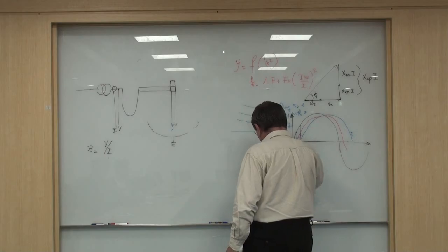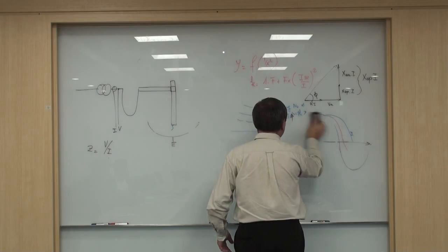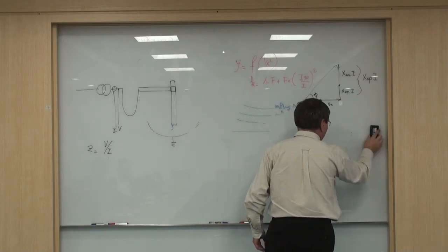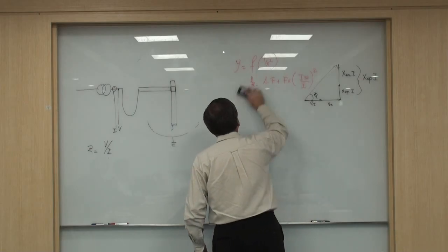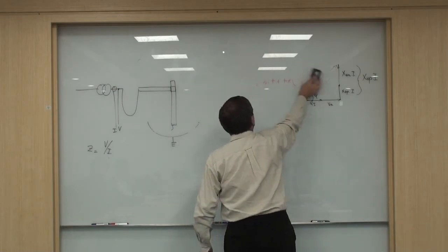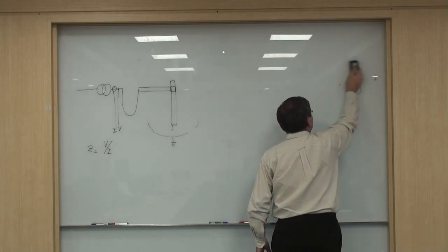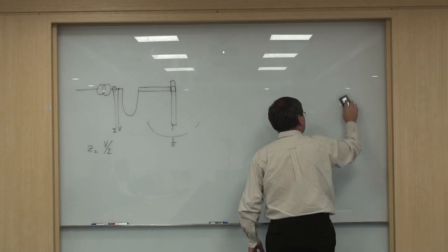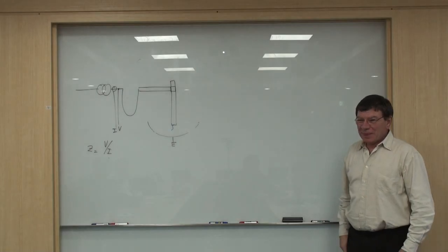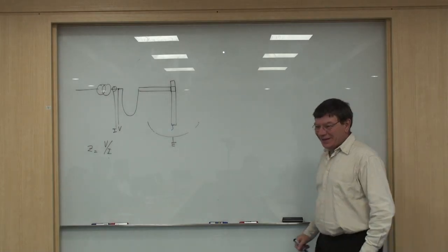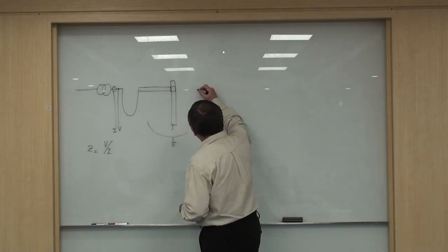In the old times, where there were no water-cooled panels and no foaming slag, there was only refractory. There was a lot of refractory wear, and people didn't know how to estimate how fast the refractory wear was going on. And there was a genius guy called Ben Bowman. Genius guy. Remember this name.